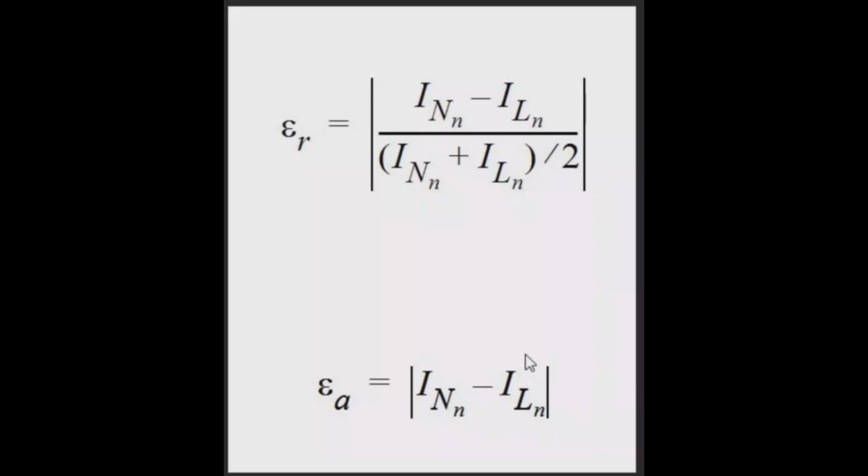in milliamps or microamps, this would be pretty difficult because the intermodulation components are going to be on the order of microamps or even smaller. If you say that the large components as well have to be converged within microamps, the problem may never converge. You know, big power amplifier circuit, you may not get convergence to that very small current.